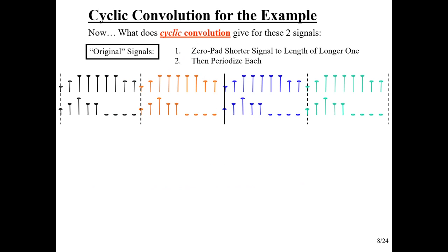Now I'm going to show you what cyclic convolution looks like. Now, in a DSP course, we would prove why we get cyclic convolution, and we would look at this. Sometimes books show it with the signal samples populated around circles. I find the circles to be difficult to view. I like to look at it this way. This is completely equivalent to the circular view that most DSP books will show you.